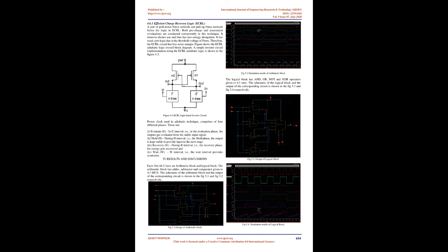4. Proposed system. 4.1 Objective. Design of portable devices requires less power consumption, lesser area, and increased speed of operation. The leakage power is increasing with the technology related to the CMOS process, which is to be reduced by implementing the same using adiabatic logic on FinFETs. To design the 4-bit ALU with 3 arithmetic operations, add, subtract, compare, and 4 logical operations, AND, OR, XOR, NOT, using FinFET technology.